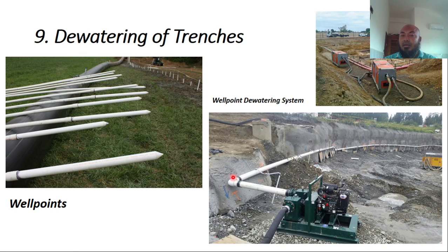header pipe like this, connecting from one well to another. This pipe is a series connection. This pipe will connect all the well points and then go to the pump, and then they will pump the water from this header pipe from each well point.